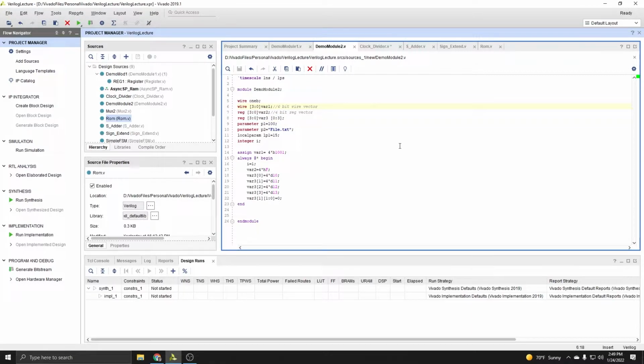Now, one other major aspect of variables is the arrays. So arrays, for now, for you all, are basically what amount to memories later on. But there are various other uses of arrays in Verilog that you will become much more familiar with if you end up taking Comp 570 as one of your electives, because you can use them with things called generate blocks frequently. But in this class, you'll not be using that, and these will simply amount to what you use as memories.